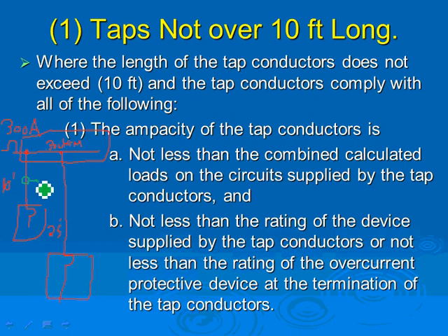The conductor, how does it look? The conductor for the 10 feet that you can tap, guys, the code says, is 1/10 of the overcurrent protection device. In my case, what's 1/10 of 300? That's the smallest conductor that you can pull. It's 30 amps, right? So for 30 amps, you have to put a 30 amp circuit breaker here, right? And what do you guys think the conductor here has to be? What's a 30 amp conductor? Number 10. That will be number 10.